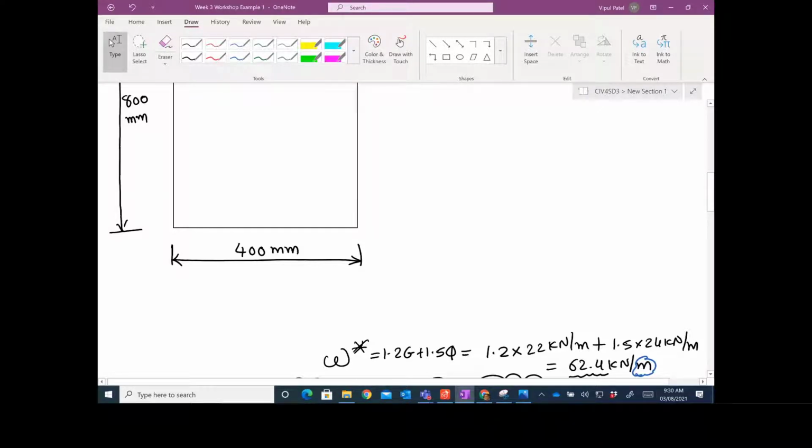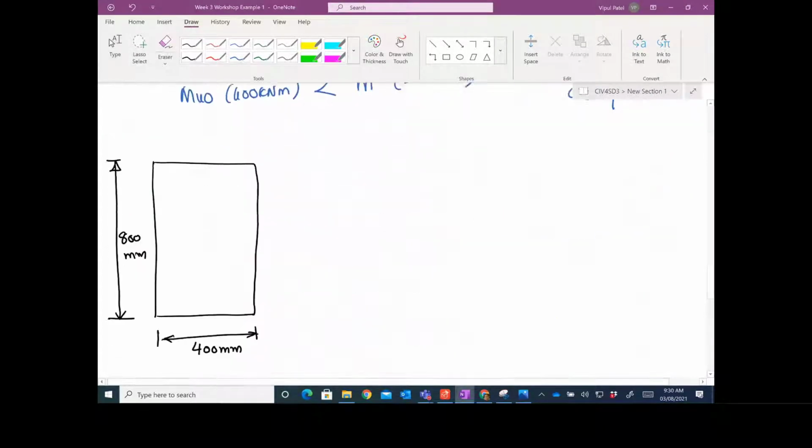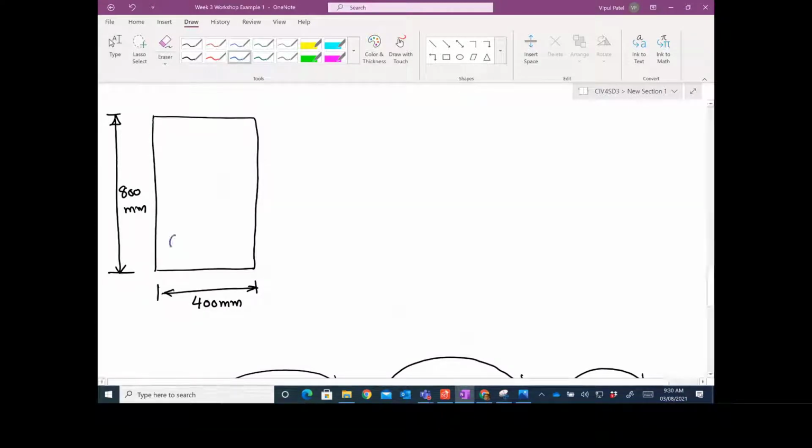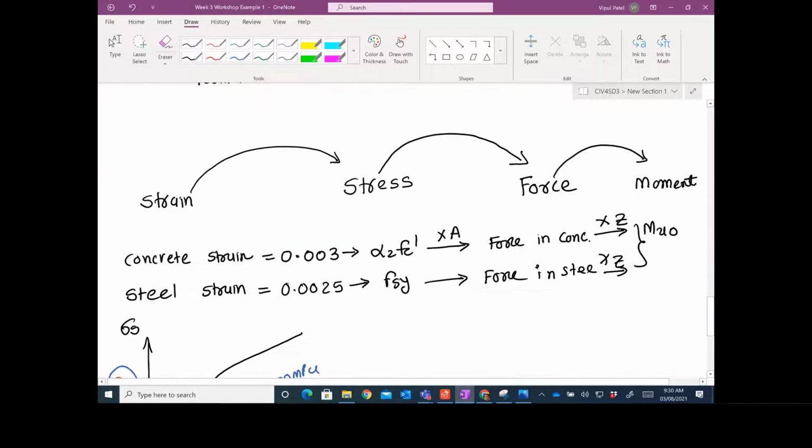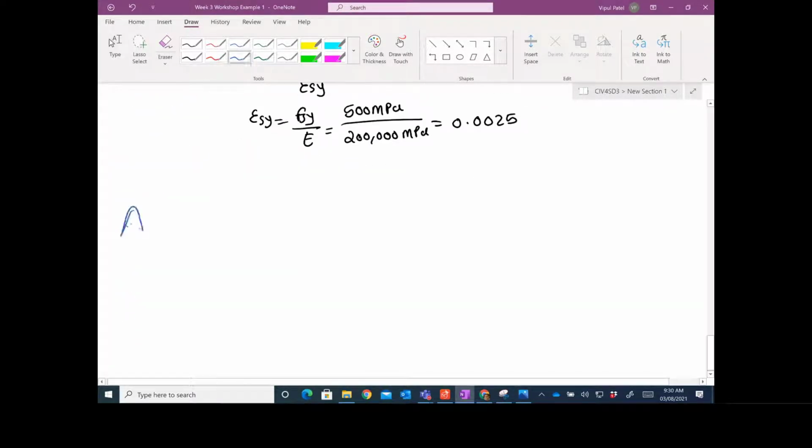Let's say probably we need to make an assumption, N24 reinforcement. Look, we can't work without the reinforcement. Let's make an assumption that we are going to use N24. We don't know how many bars we're going to use, so let's make a bold assumption. Assume N24 reinforcement. This is just an assumption. Please note, in the beam, we normally use 20 millimeter or 24 millimeter reinforcement. If you use too small, N equal to 10.